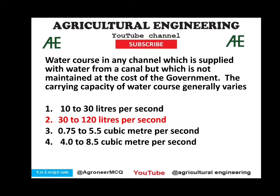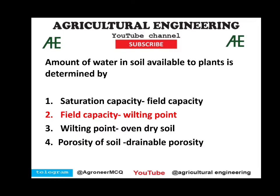For a water course, any channel which is supplied with water from a canal but which is not maintained at the cost of the government, the carrying capacity generally varies between 30 to 120 liters per second. Amount of water in soil available to plants is determined by field capacity and wilting point.